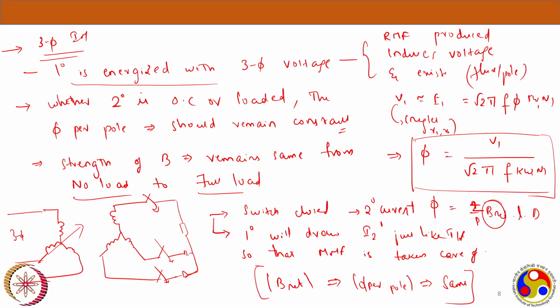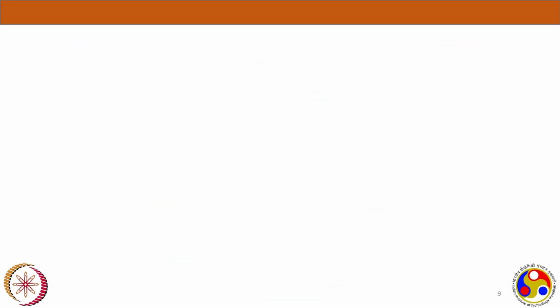Now let's get back to our original discussion where I have two currents, right? I have connected I2, that is SE2 over the square root of R2 square plus SX2 square. So this is the actual condition we have taken, when the machine is running and your slip is not at 1 anymore. It's not at standstill anymore.